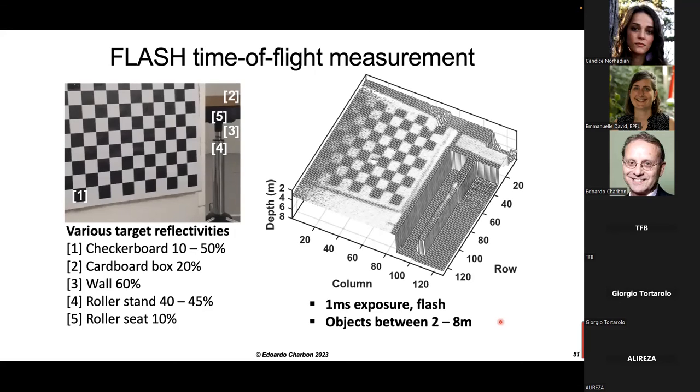Now, one thing that I would like to notice is the fact that since we have a single TDC for a cluster of 8 by 16 pixels, we have to use a mechanism known as decision-making detectors, if you like, that are basically fast logic that is used to take the input coming from all the photons, from all the detectors in the cluster, and redirect it to a single TDC, maintaining the information about the origin.